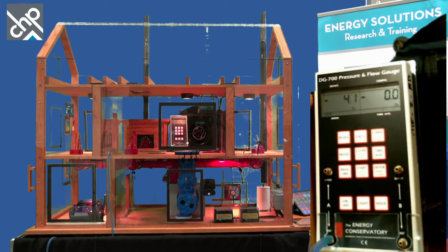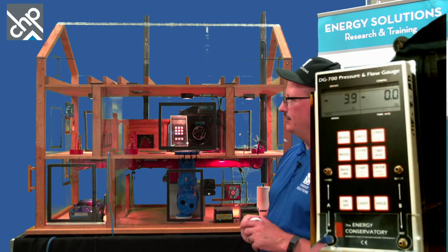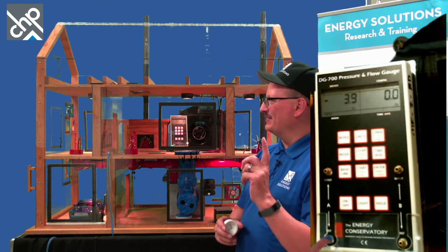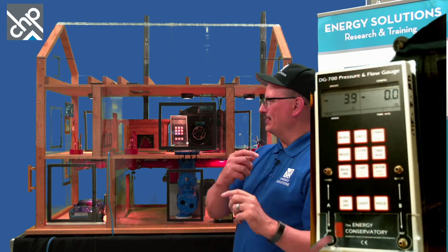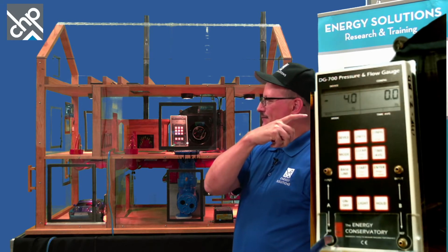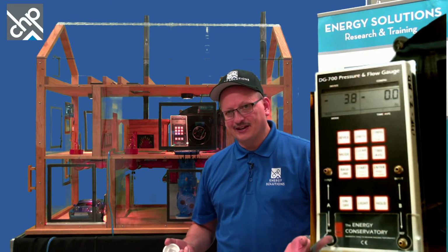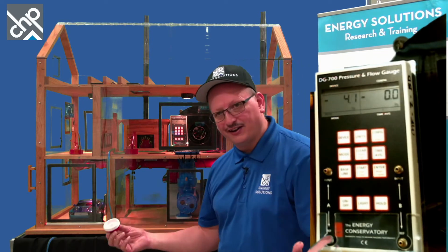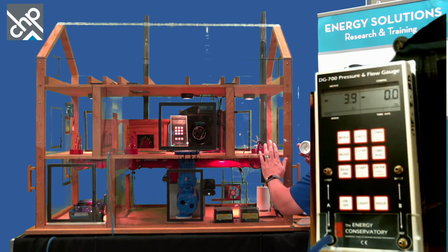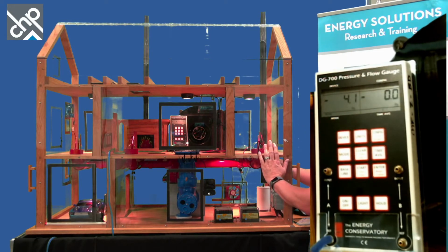So what happened to the pressure? I'm going to point to my manometer that's overlaid. We have a negative number there. You saw that I opened a supply leak, and so it's actually making the building suck. An easy way to remember that is supply leaks make the building suck. So supply leaks suck. You can also see the streamers here, they stop moving. I'm going to put the plug back in, and let's see what happens. The pressure equalizes, and now the streamers work.